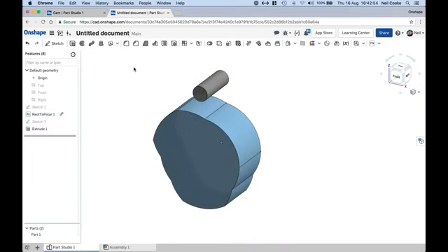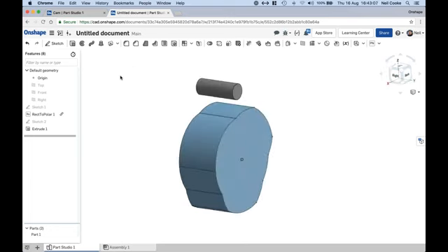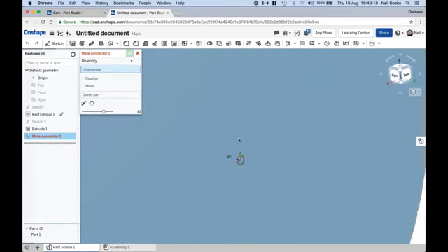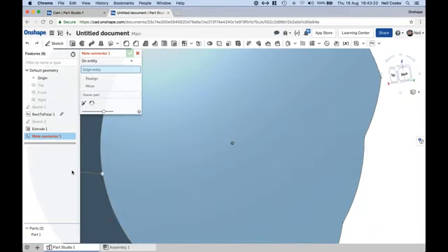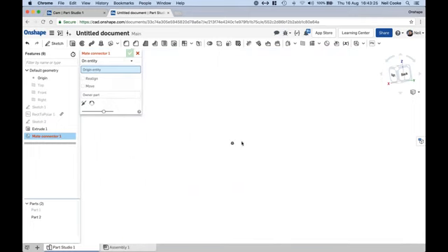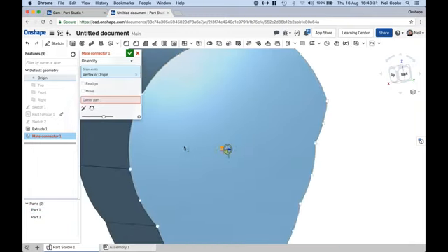And the only really other trick is with regards to making these assemble and to add them on. You can either put holes through the center of the cam, for example, to position onto a shaft, or just for the sake of argument here, we'll do a mate connector and just add it to this point at the moment. Okay, so we want it on. I'm just going to hide that point and hide that so I can pick the origin. Okay, so I've selected the origin.